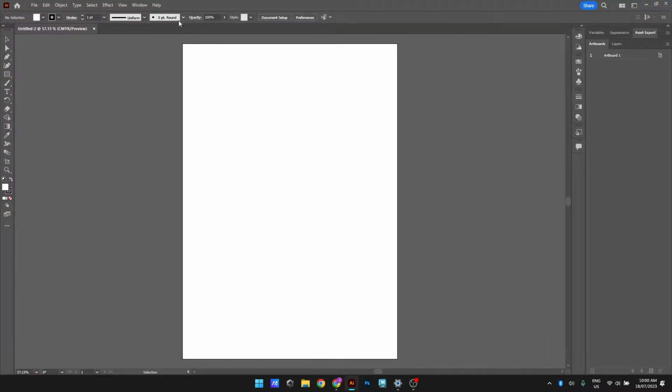Now I've pressed create. What we're going to be using for the exterior is the rectangle tool, and I'm going to just click and set this to the scale that I want. So I want my building to be 12 centimeters wide by 2.5 high, and that will create a scale at 1 to 100, 12.5 by 2.5. And I'm then going to click and make this an L shape by making my width on the second one 2.5, the height can be 12.5.